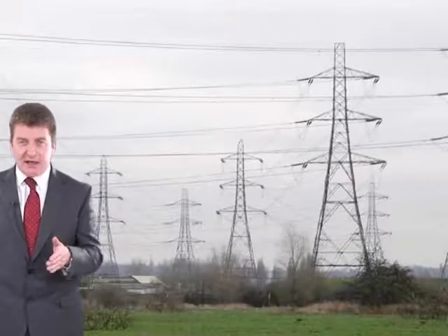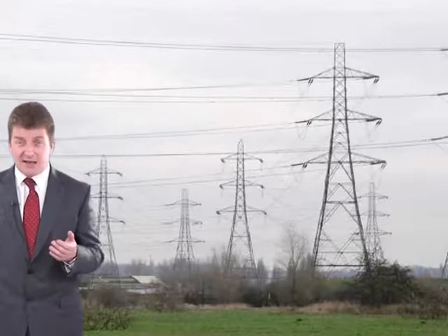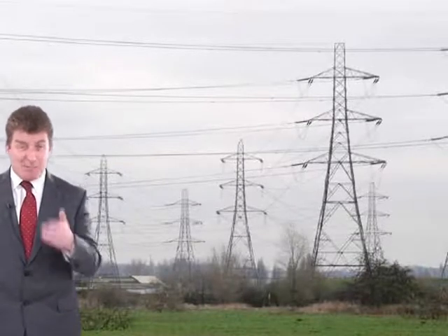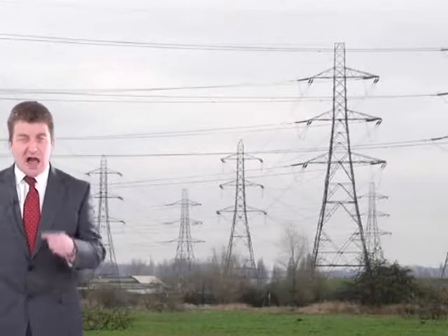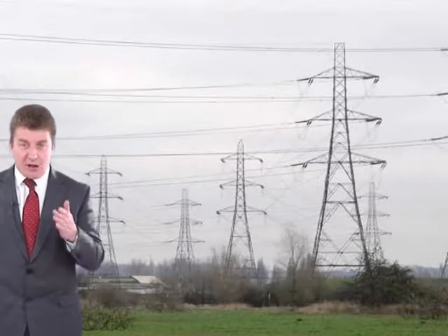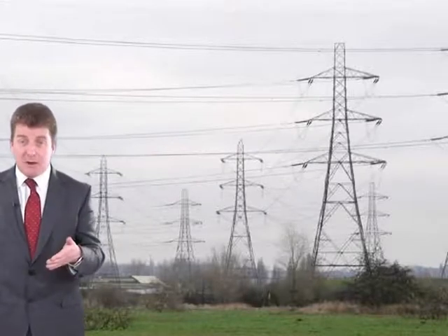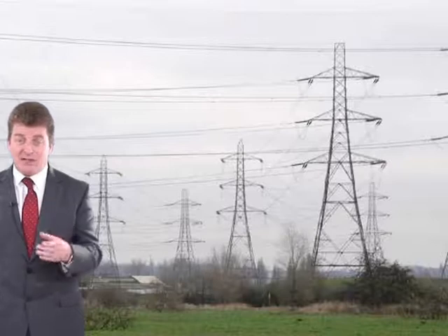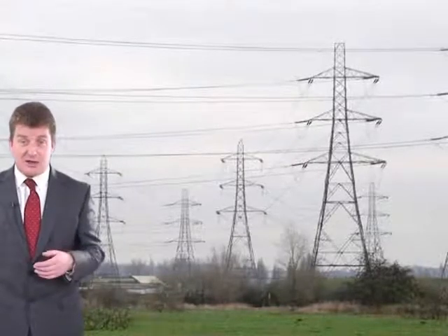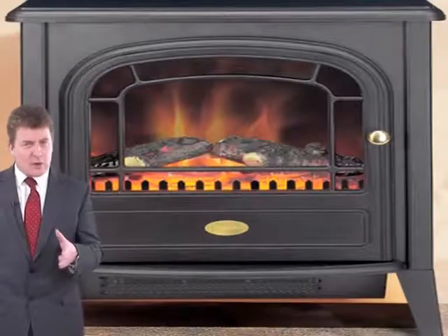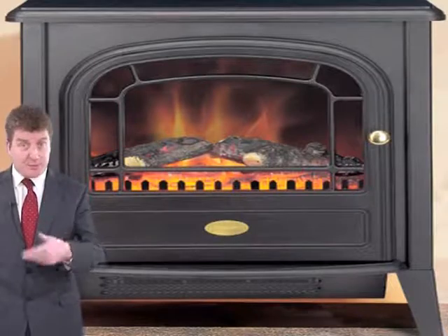Now, the dissipation of electrical energy is often undesired, particularly in the case of transmission losses in power lines, and that's why they transmit it at high voltage. High voltage transmission helps reduce the losses by reducing the current for a given power. So by transferring at high voltage, it reduces the current, because it's current that causes the loss of energy. On the other hand, Joule heating is sometimes useful. So we don't want it in high voltage cables, but we want it in other things.